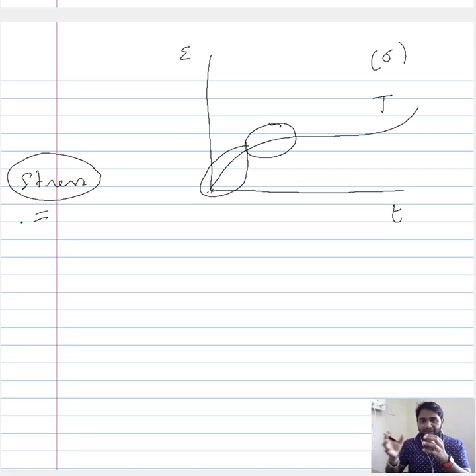One is by creating the annihilation of the dislocations, the other is by rearranging the dislocations. And once the temperature is able to enhance the plasticity, you have a balance between the restricted plasticity that is caused by stress alone and the enhanced plasticity that is brought about by the temperature. This balance is what is responsible for the steady state creep.